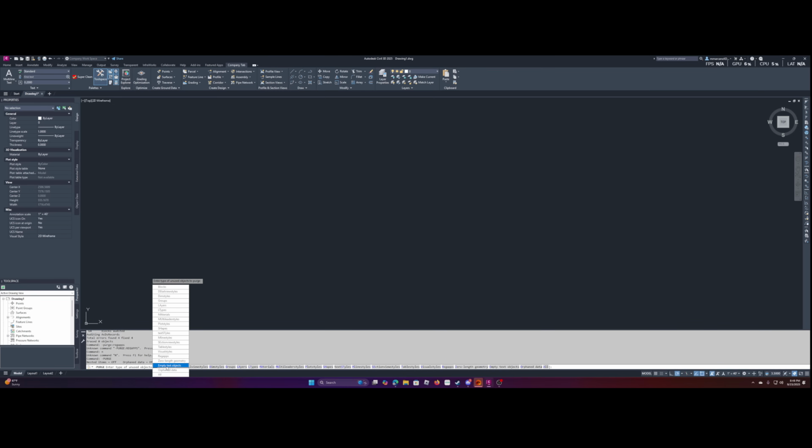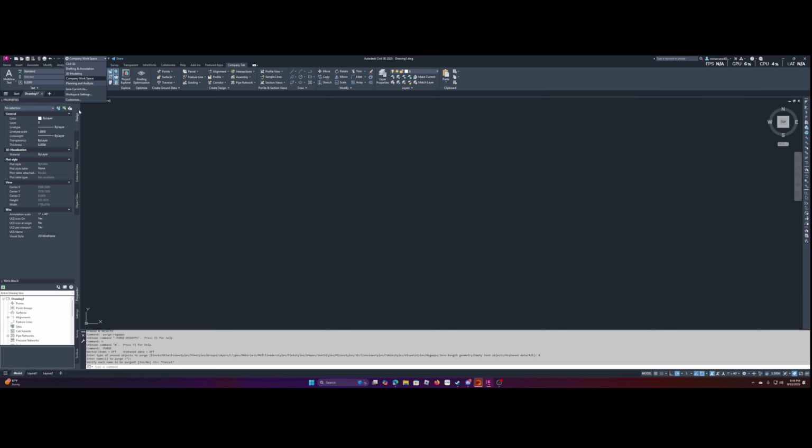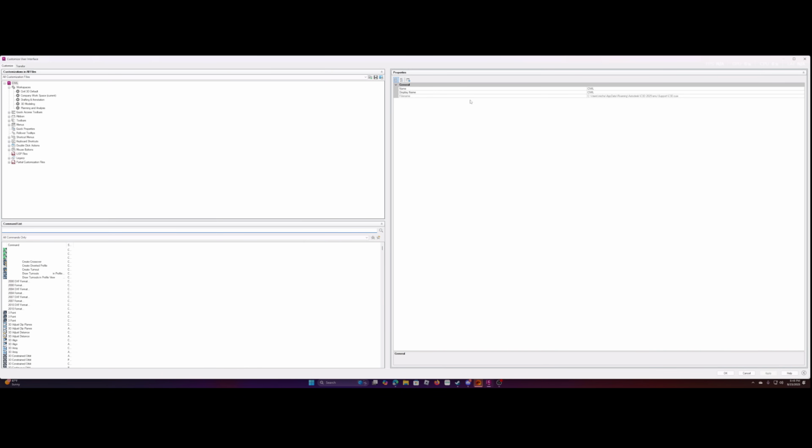So here you select regapps, enter names to be purged. It's not supposed to be no. You're supposed to leave it as an asterisk or a star, and then hit enter, and then verify each name to be purged. And here I would say no. Okay, so let's fix that really quick. That's actually a great little lesson right there, right? Let's go ahead and fix that.